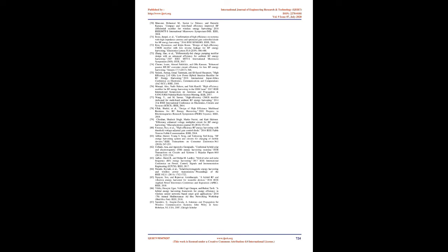Wen et al., 2018, proposed a hybrid energy harvester that uses RF energy and vibration energy. They describe a hybrid model that combines RF energy and a thin piezoelectric film of polyvinylidene fluoride to harvest energy for a frequency of 915 MHz and at a vibration of 15 Hz. They have used a multistage voltage multiplier along with a Dickson RF to DC converter. Results claim that a power of 3 µW and 1.8 µW is generated by harvesting RF energy and vibration energy respectively.